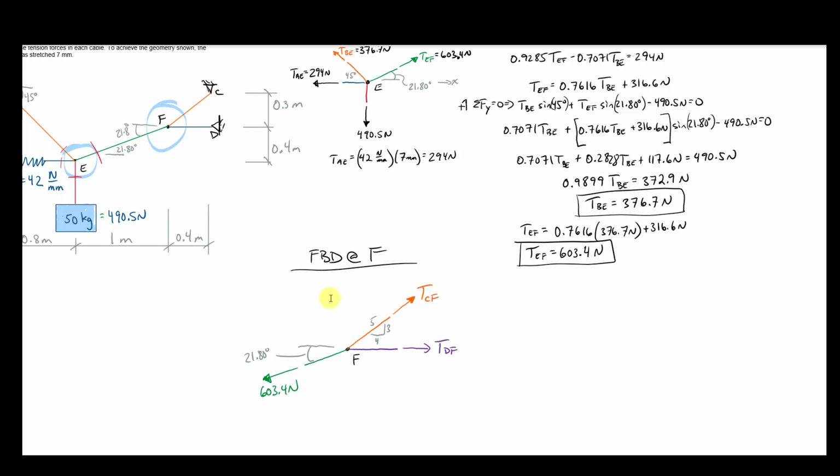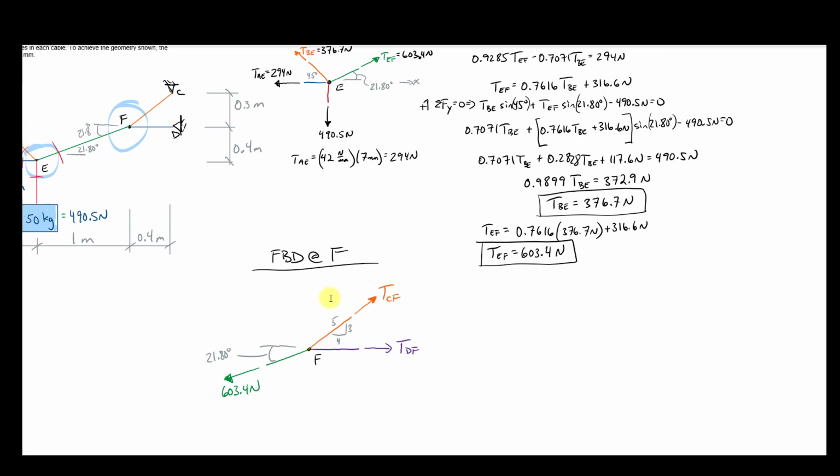At the cut surfaces, put all the internal force vectors that will show up. This one, we already know. These other two, we don't know their values yet. I give them names. I turn names into numbers because numbers are answers. Names are unknowns. So I like to identify what I don't know and then turn it into something I do know. All right, looking at this, sitting back after drawing it, saying, oh, that's a great looking free body. I'm very proud of myself. Since it's so clear, I should be able to see exactly what I need to do next.